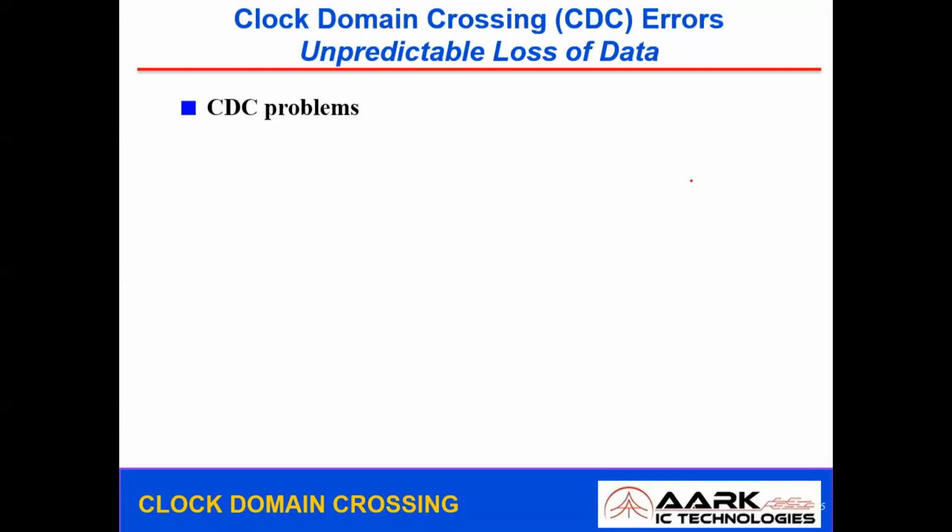Snapdragon, for example, is an SoC, which consists of all the blocks required for mobile communication. Each and every block, either it might be your GSM module, or your GPS module, or your memory element, or your processing unit, might operate at different frequencies. You cannot expect all blocks to operate at the same frequency, so we cannot avoid them. Multiple clock domains in a few scenarios is mandatory, and we should have these multiple clock domains.